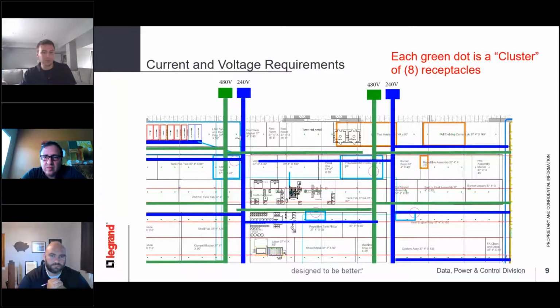But the other thing we were looking at was the amperage. They said, well, I have 6,000 amps coming in, possible amps coming in on each phase. Where do we want to go with it? Originally, we started oversizing the busway and said, well, that's not going to be the case. Most of these aren't going to be used. So we came down to a rule that about 65% is roughly where we want to be of your total load. Now, we always say, use your best judgment as well too.